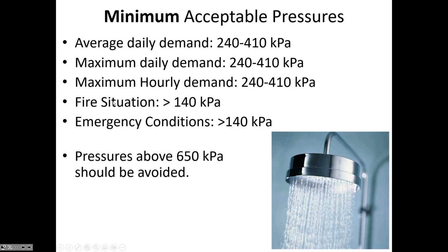And the water pressure to begin with is only about 50 psi at my house. So if I go with this smaller pipe, it'll be the sort of thing that if one person flushes the toilet while you're in the shower, suddenly it changes temperature because the pressure drops so suddenly. So I'm going to go ahead and spend the money and get the 1-inch pipe instead of the 3/4 inch pipe because I want to maintain a good acceptable pressure.